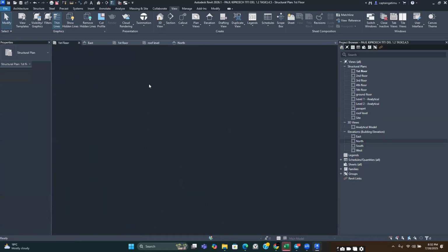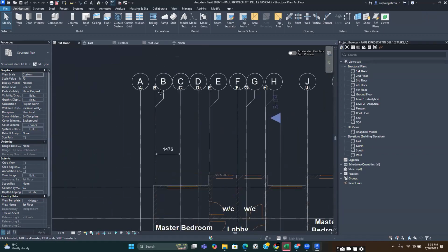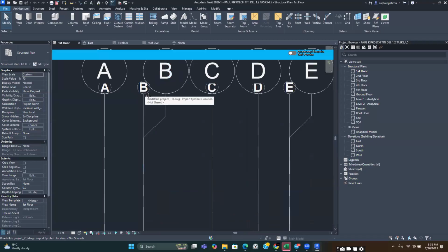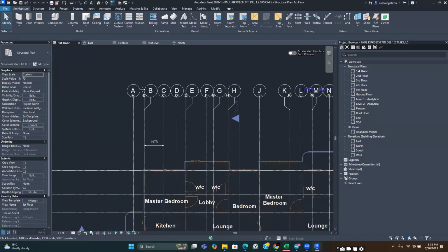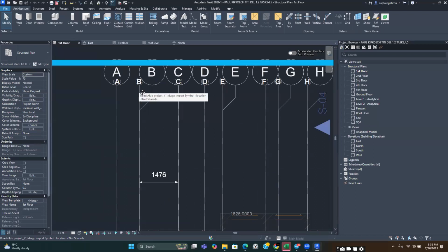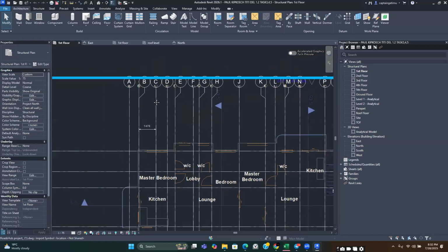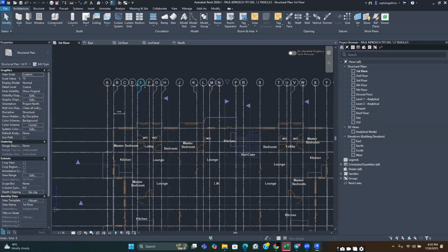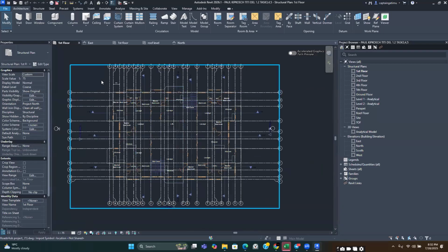Oh, I get you now. So we've created the additional grids in Revit, but still, the grids that we linked into our model in the CAD file still exist. Is that the issue? Yeah, exactly. Okay, so that should not cause you any concern because later on, once we are done with the modeling, we are going to remove this CAD file and it is going to go away with its grid.